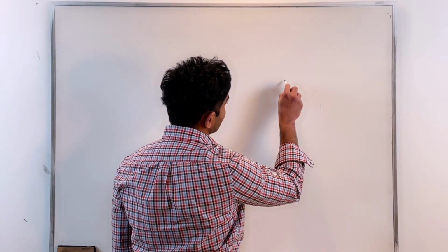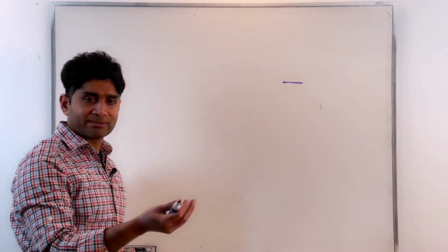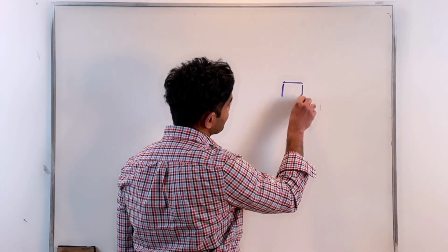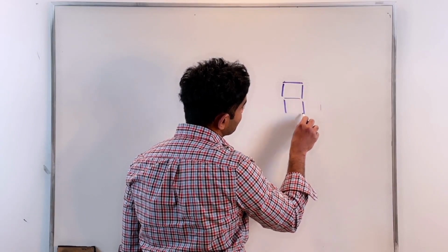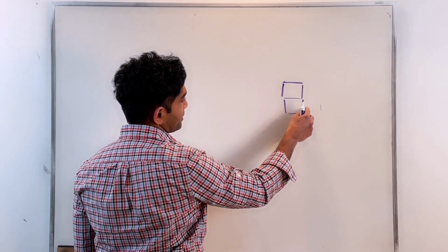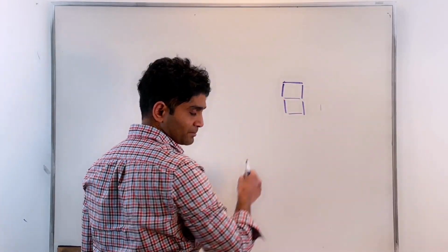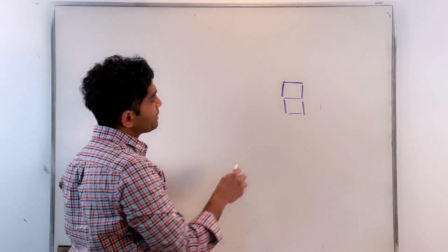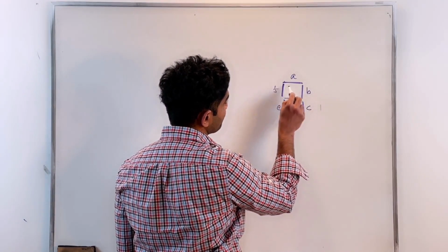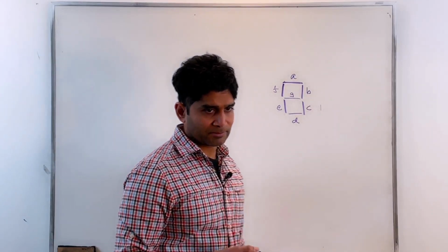In terms of the display itself, it's actually very simple to understand. You must have seen it, because you operate your calculators all the time. You have these 7 segments, right? To display a single decimal digit, I would have 7 segments. One, 2, 3, 4, 5, 6, and 7. So that's the 7 segments. Let me call them A, B, C, D, E, F, and G. Now you can imagine each segment to be an LED, a light emitting diode.